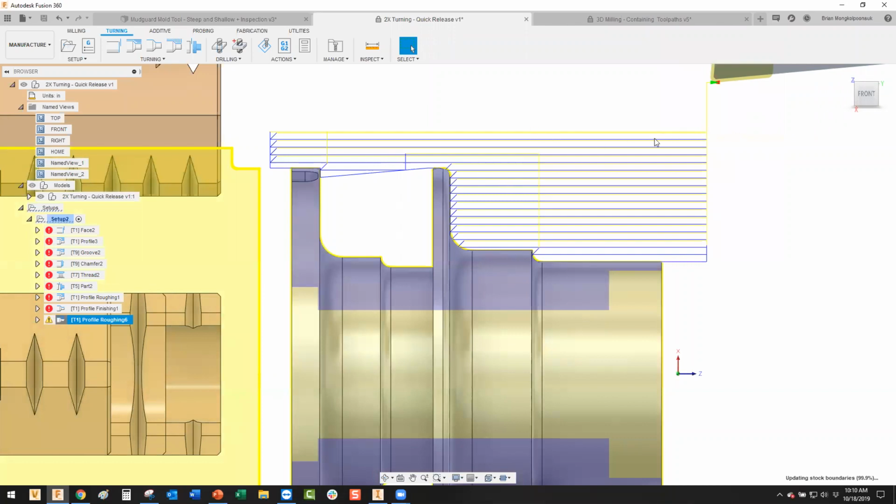to have more control, or they gave me more control here in Fusion to maybe cut the air a little bit to make sure that we're coming in the way we want to come in. Maybe you don't want your first cut over here to actually cut the model. Maybe you want to see one air maneuver first, and then go into start roughing out this model here. So you have control to increase the height of the clearance here for the X direction and the Z direction as well.